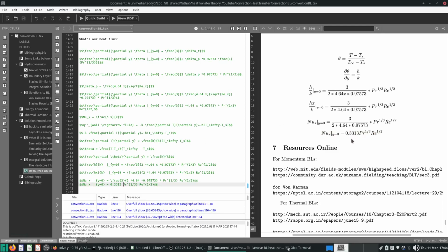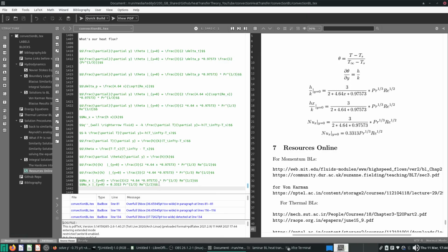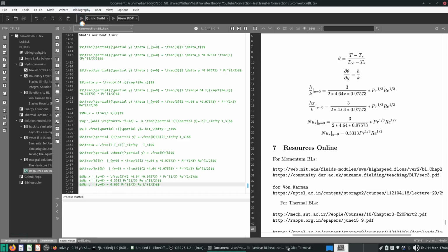Okay, Nu_L, you can do it yourself. I'm not going to do it for you. Nu_L is just twice of this. I'm not going to prove it here. You just have this times 2, so you have 0.663. Just to make sure, I'll have Re_x here, and this one is Re_L. This one you prove yourself. I've done it so many times.